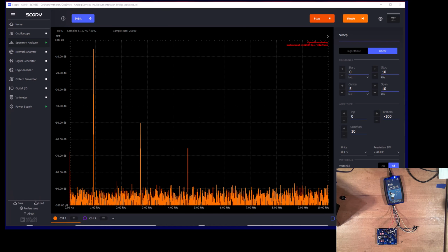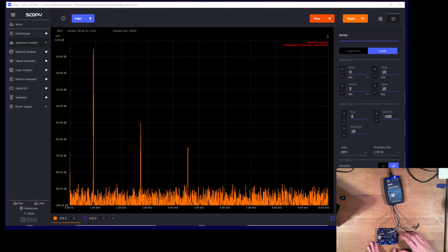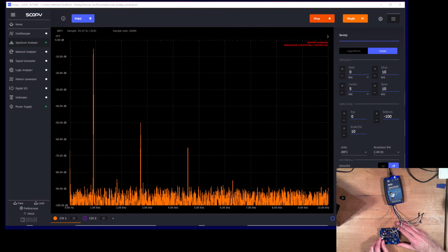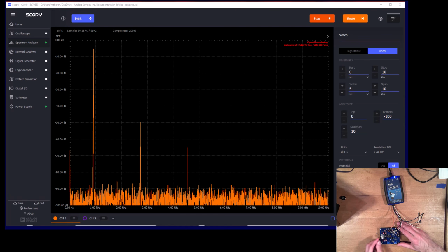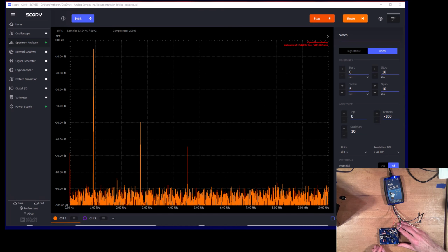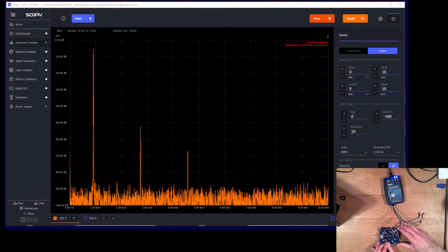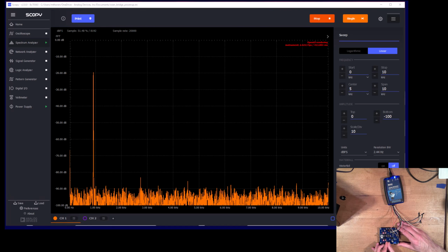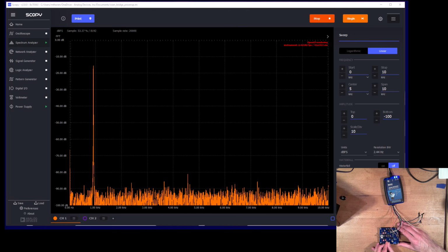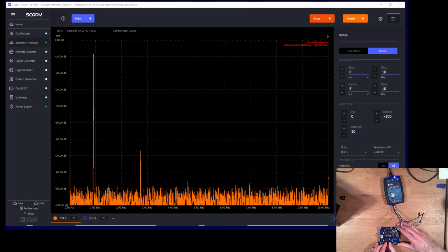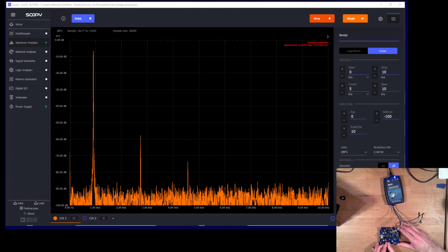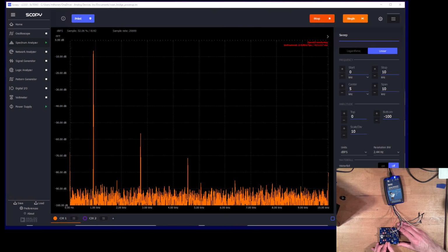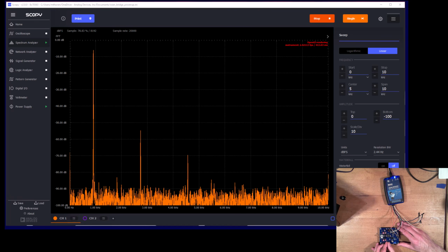Okay, before we switch over to light bulb gain control mode, let's just remind ourselves where we were as far as performance was concerned. So here I am set to a 1 kilohertz fundamental, and if I adjust the diode gain down a little bit, look at that. I can get the distortion down a bit, but boy, it's just on the edge of not oscillating. Okay, so here I can tweak, and boy, you see what I mean? It's just not really that stable.